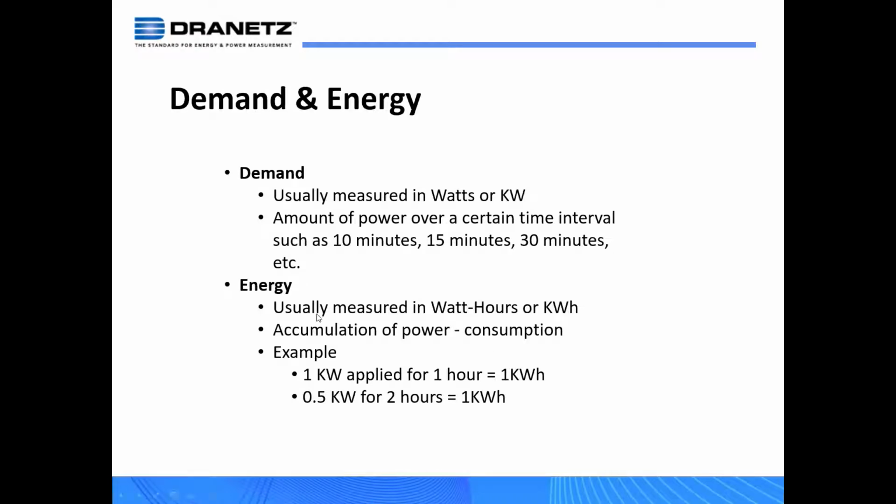And what is demand? It's the amount of power over a certain time interval. And that's your demand interval, usually set by your utility, and that's typically 15 minutes, maybe 10 or 30 potentially. The metering can be changed, but a lot of times you'll see a 15-minute demand interval.